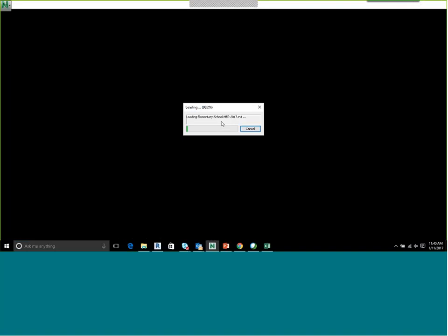I typically bring in the entire Revit model. Other people typically do a selection from a 3D view and export to Navisworks as an NWC file. The problem with that is every time you want to refresh your Navisworks model, you've got to go to Revit. You have to find that 3D view or recreate that selection again and then re-export it. It's very time-consuming to do that.